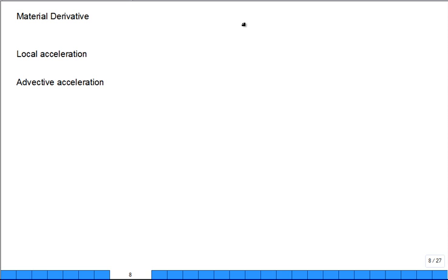If I wanted to say I have a velocity field, and I wanted to get the acceleration of that velocity field, it's so tempting to take the ordinary time derivative. Don't do it. Do a special derivative called the, guess the name, material derivative, and they give it a slightly different notation so that it's emphasized that this is the material derivative of the velocity field. That will give you the correct acceleration field.